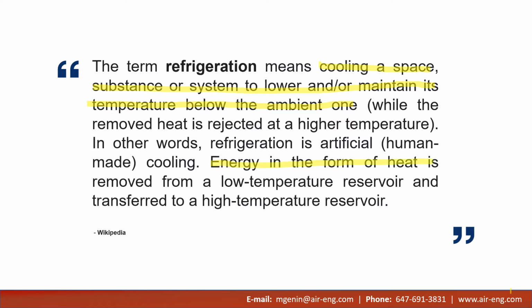Energy in the form of heat is removed from a low temperature reservoir and transferred to a high temperature reservoir. And this is really what I want you to think of when we think of refrigeration. It is a movement of heat from one reservoir to another, and it's not so much focused around the cooling effect. Most people think about the cooling effect, but it's important to think of refrigeration as the movement of heat from one area to another, because refrigeration can also be used as a means of heat production, not just cooling.